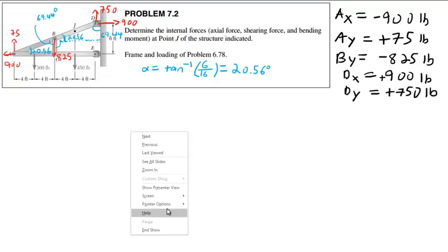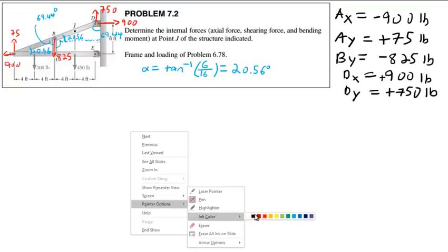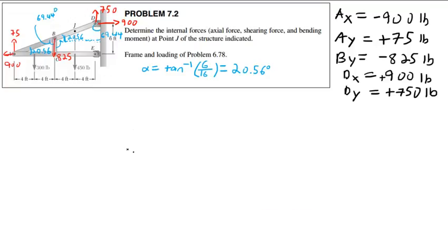Okay, so now I'm going to draw a nice big free body diagram of member ABD. Because what I really want to do is, remember in the previous lecture, we had these nice horizontal beams, and it was really easy to do a sum of forces and things like that along there. That's what I want. I'm trying to transform what we have here into something with a nice horizontal beam where I can very easily find my axial force, my moment and all that kind of stuff.